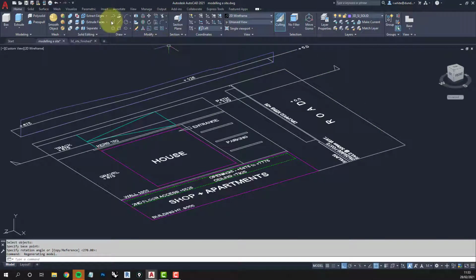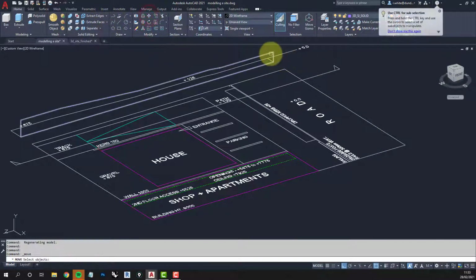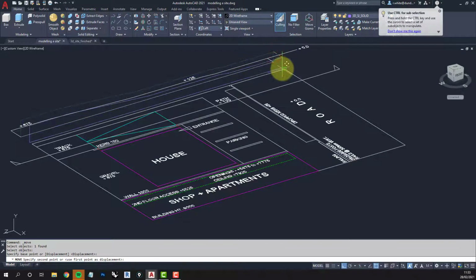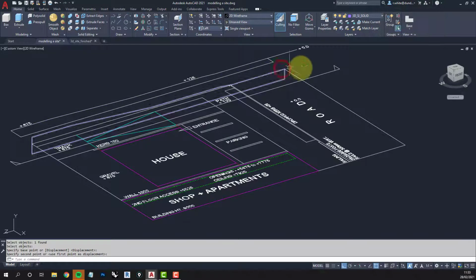Okay, now let's put that into position on the model. So I want to move this now from endpoint, and let's just place it on the corner here. And then if we extrude that, the extrusion should work, even though the UCS is facing the side of the model. The extrusion should work perpendicular to the object.